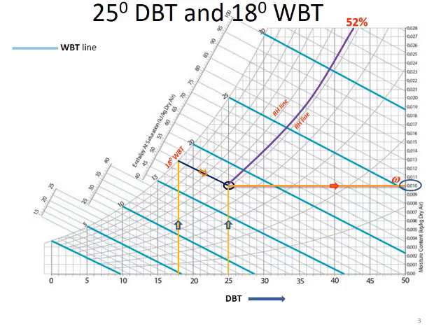Suppose you cannot approximate, then you can keep a scale between 50% and 60% along the WBT line. First calculate the total distance gap, then find the gap between that point and the 50% line, and then you can interpolate based on that distance to find the RH at that point.